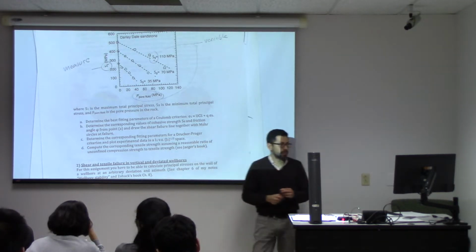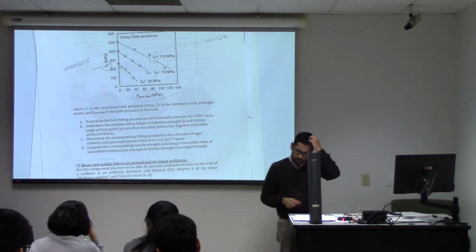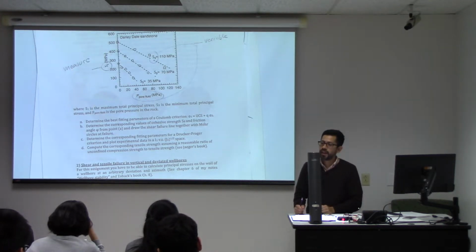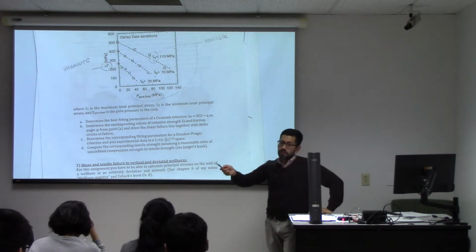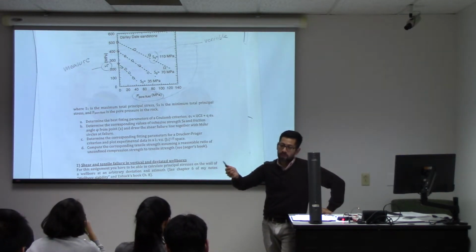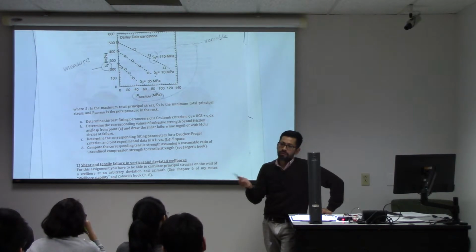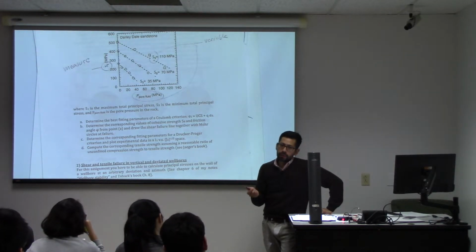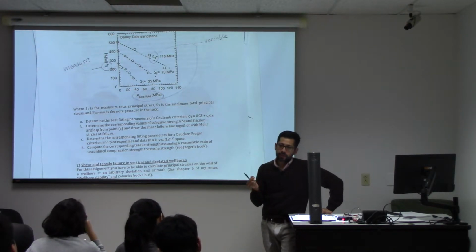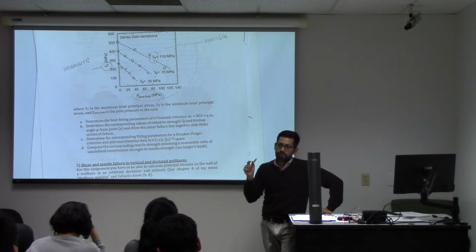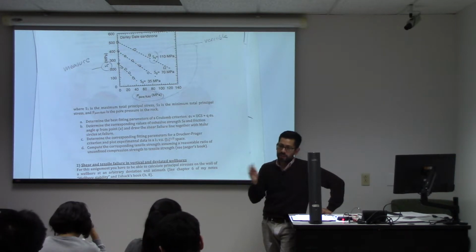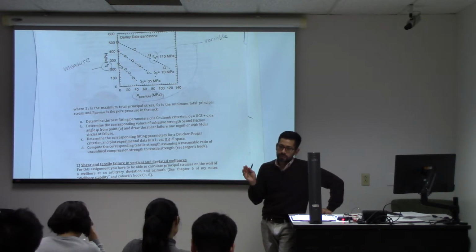Yes, Robert? Are we just going to use Terzaghi effective stress, or are we going to go about and find out the real one? Terzaghi. You're just going to use Terzaghi effective stress. Actually, that's a good question, because many people are tempted to use Biot for failure as well. But the Biot stress is accurate to compute the deformations when there are changes of effective stress.